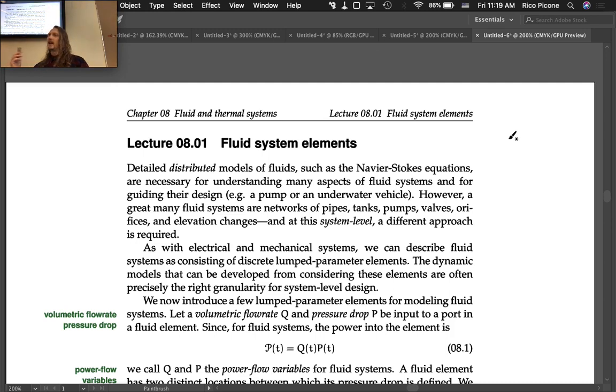If you want to design the shape of an impeller, you're going to want to know how that fluid's moving around, see where you're getting fluid separation, see where you've got vorticity that develops. You want to see those sorts of things, which requires the Navier-Stokes equations to explore. But when you're looking at a system that's got 3 pumps in it and 2 tanks and these pipes, that sort of analysis isn't really going to be helpful.